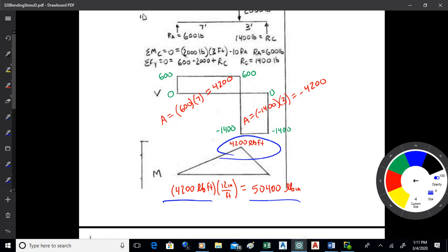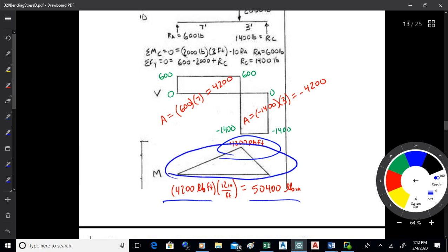All right, so that's step the first there, is to find the maximum moment, because that's what I'll design the whole beam for. All right, now, that's kind of civil stuff, you're taking beams usually out of a catalog, and you're putting a building together. You're not going to custom design a beam for every application. Now, I would contrast that with building like a vehicle or an airplane or something like that. That's when you might, if I were putting this into something that I was going to mass produce, which buildings are not mass produced, custom design the cross section of that beam so it kind of peaks at 7 feet, because that's really where I need the strength of it.